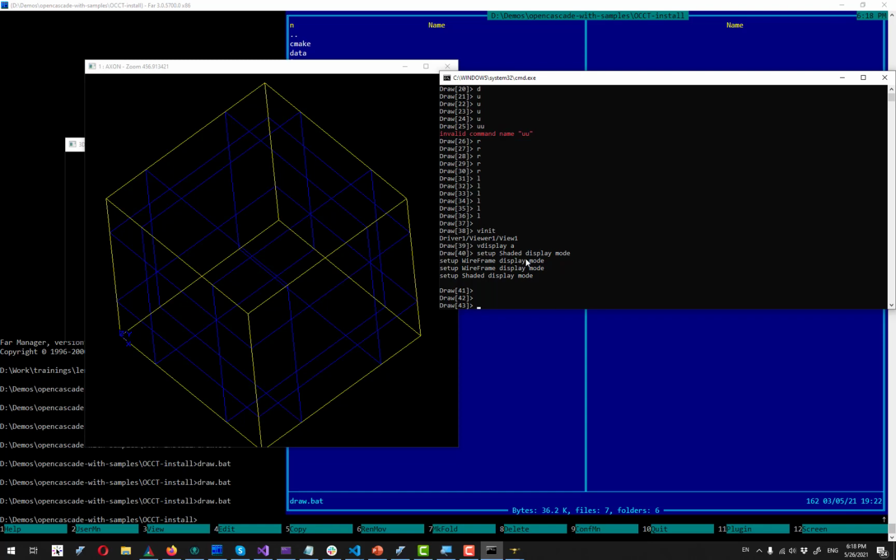Then what we can also see here is, for example, this nbshapes command, and we can give it the name of our solid, and it will print the summary of what we have inside our shape. As expected, for a box shape, we are going to have 8 vertices, 4 on top and 4 on the bottom. Then we have 12 edges and 6 wires and 6 faces.